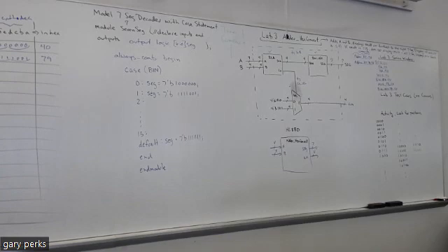So what does this anode bit have to be for there to be any chance for a segment to light? Well, this side of it, though. Okay, this side of it has to be a 0 to make this side a 1 for there to be any chance for a segment to light, correct? If the AN is a 1, and then this common anode connection becomes a 0, is there any way I could light a segment?